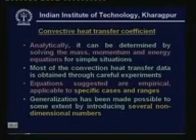And fortunately, because of the huge amount of work done in this area, you have correlations for almost all practical situations. So, you have to look for them in suitable heat transfer data books and textbooks. And to some extent, generalization has been made possible by introducing several non-dimensional numbers. Probably you remember from your basic course on heat transfer that several non-dimensional numbers such as Reynolds number, Nusselt number, Prandtl number are introduced, and generally the correlations are given in terms of these non-dimensional numbers. This will generalize the correlations to a large extent.